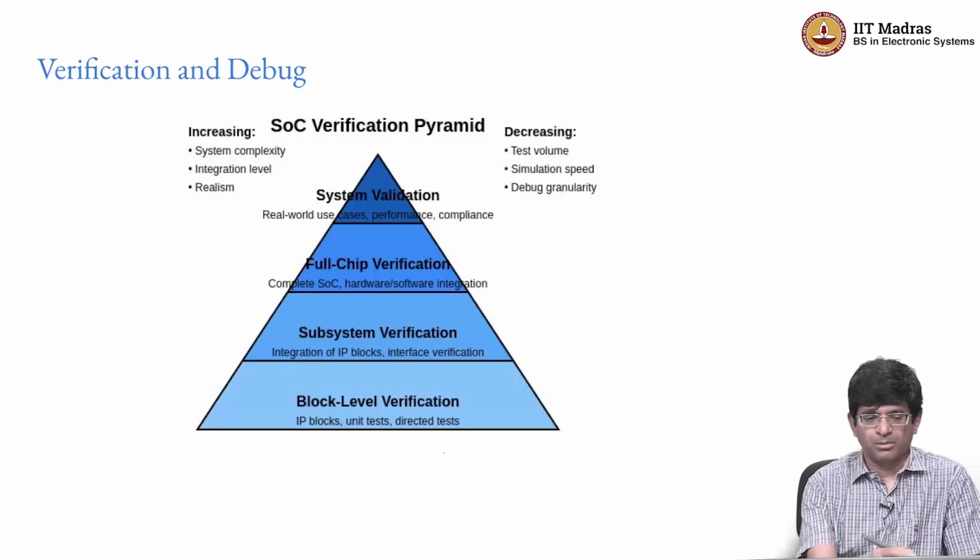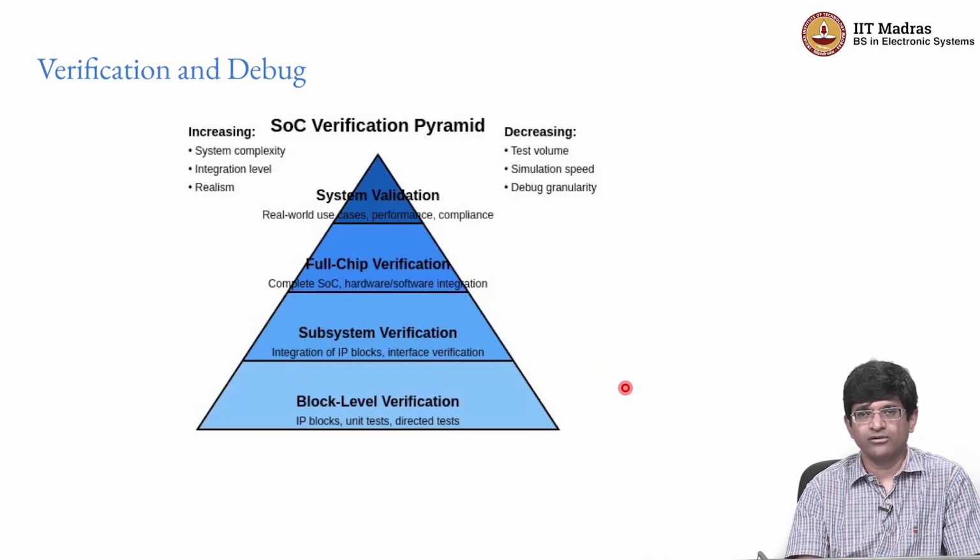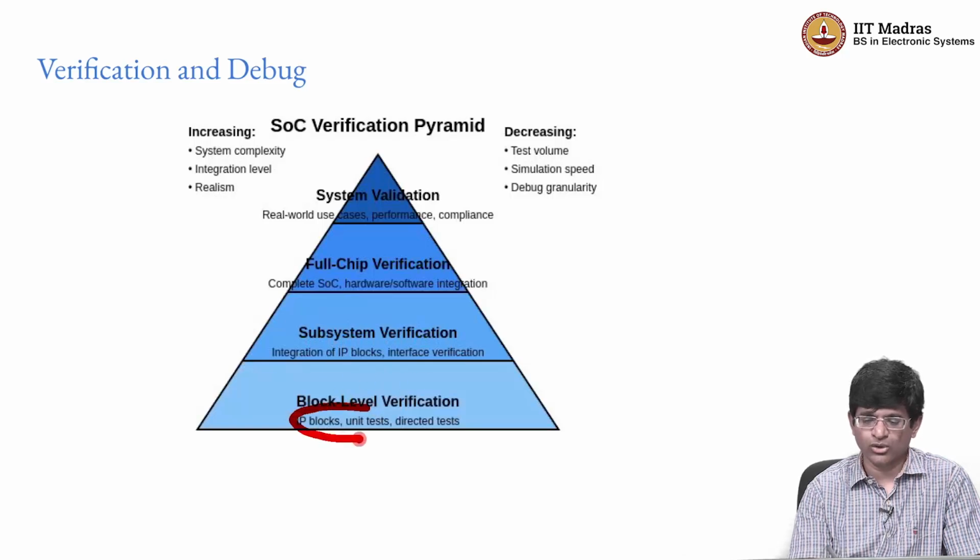Now, power aside, the next big challenge as far as SoCs is concerned is verification and debug, and it's useful to think in terms of a pyramid, right. And of course this applies not just to SoCs but any kind of large system design, where we start off with the so-called unit tests, which are individual IP blocks being designed at the individual block level.